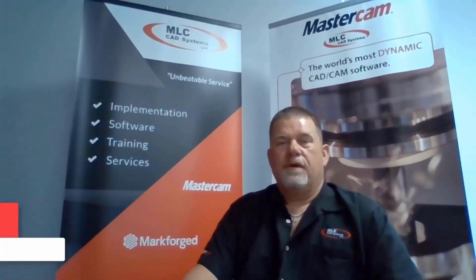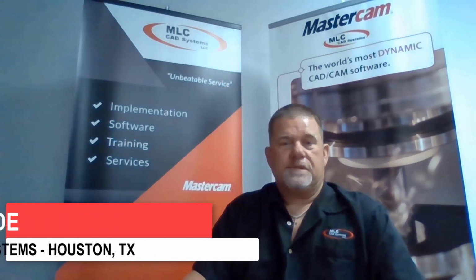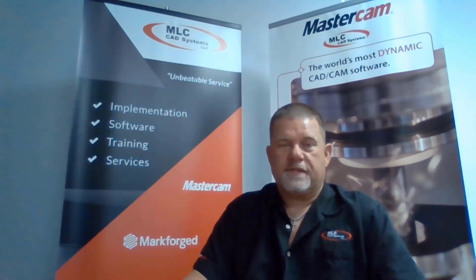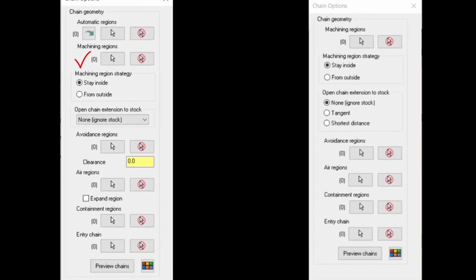Hi everyone, Bo Rohde coming to you from Houston, Texas. And I'm here today to talk about automatic region selection, as well as other enhancements inside of our Mastercam 2022 2D dynamic toolpaths. Let's take a look. The first thing you notice is the chaining dialog has a few new options, including automatic regions, where you can select a region and Mastercam will define your cut region, your avoidance regions, as well as air regions automatically.